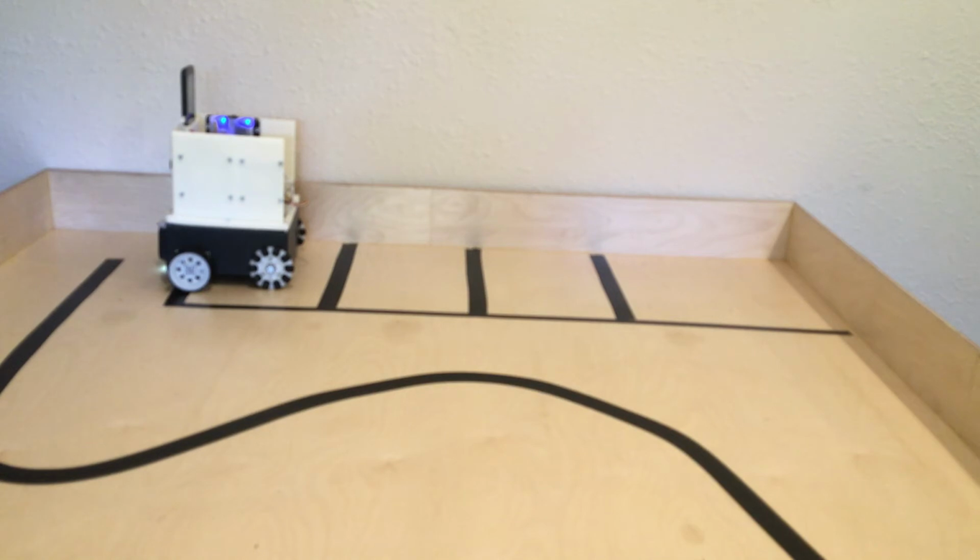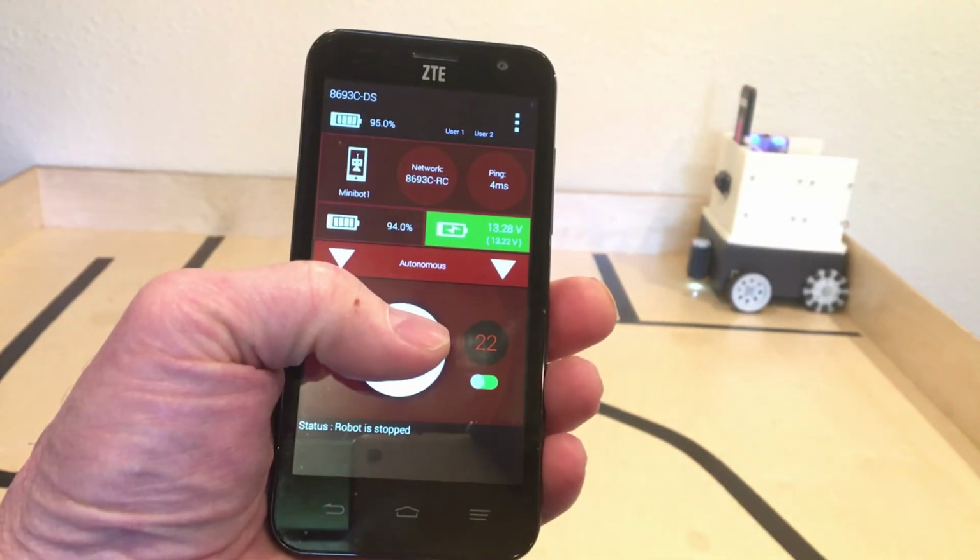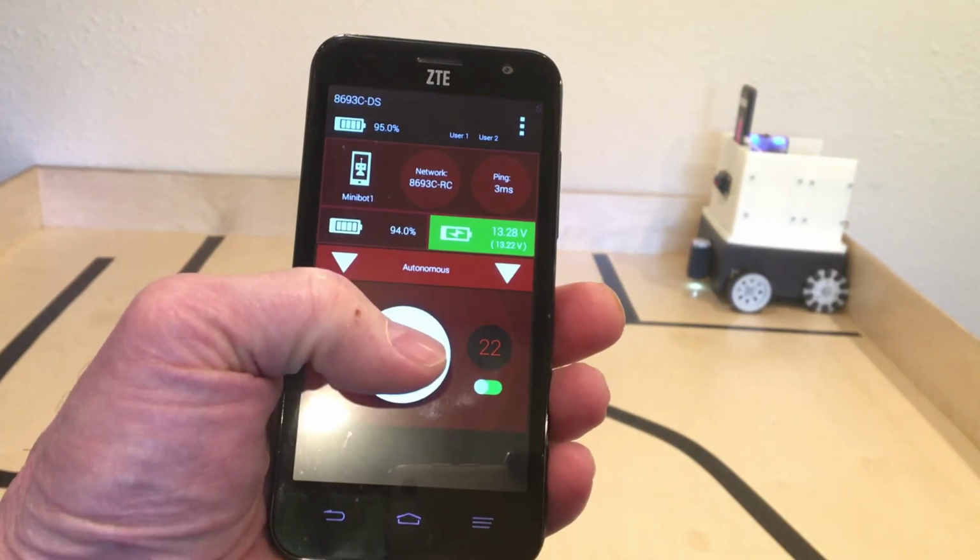One additional test you can run is to validate there is a light on from the color sensor located in the front of the robot. This light should come on after the init button is pressed. This sensor is pointing towards the floor and is used to count lines. If the light is not on, the color sensor will not send the correct information back to the robot, and the robot will not count any lines. Notice also there's a display on the driver station that increases as the robot is counting lines.